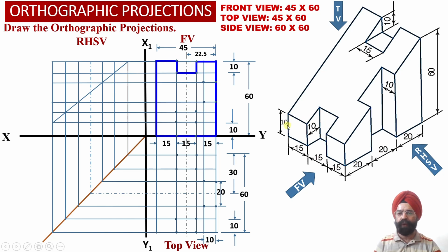So it is this boundary. This is the total boundary of the solid which will be visible to the observer from the front view orientation. Then we see that these 2 surfaces at the front face will be visible to the observer, and they are parallel to the vertical plane. So they will be represented as true shape rectangular cross sections visible from the front view orientation.